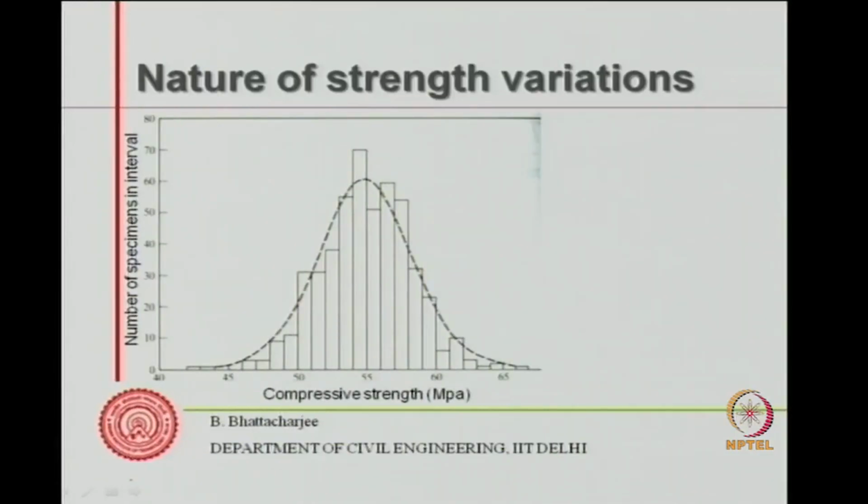Now let's understand the procedure. To understand the procedure, the first thing I must understand is the nature of variation of concrete strength. Supposing I have a concrete strength, I thought the mean strength would be somewhere, let us say, at 28 days age I am talking of at the moment. I decided that it should have some kind of a mean strength of, let us say, 55 or so. This will be valid for any other mean strength also.